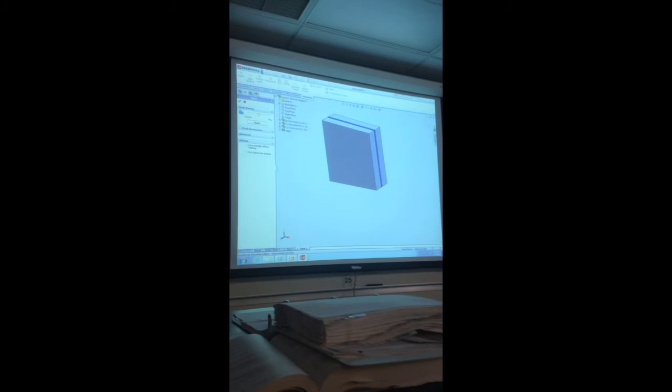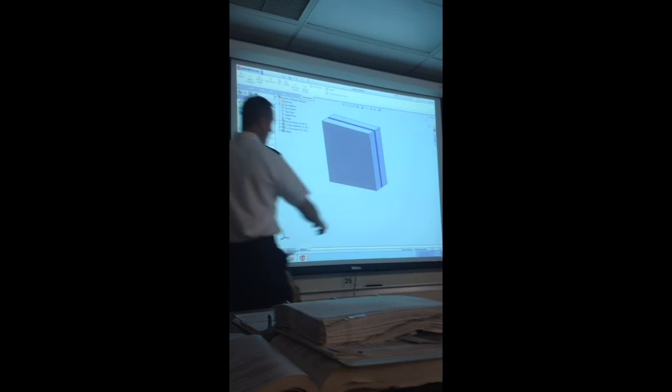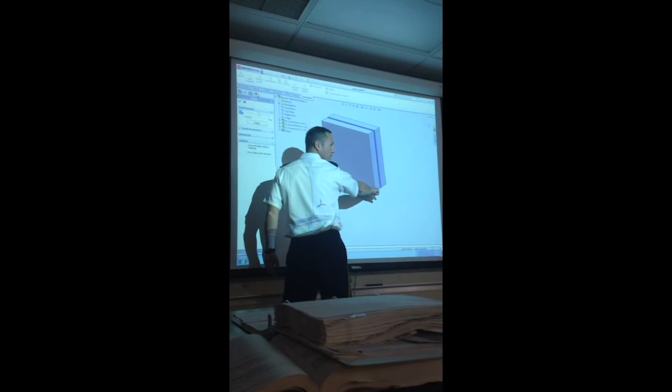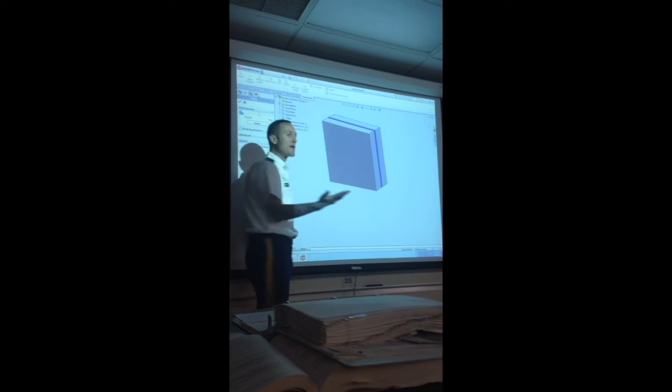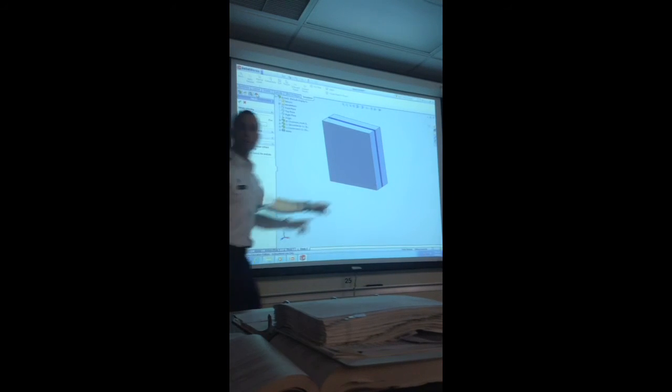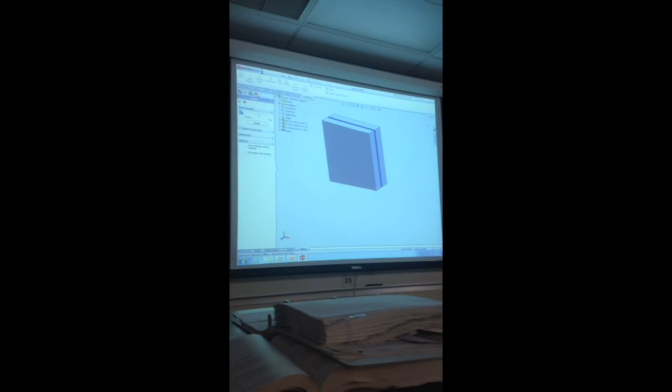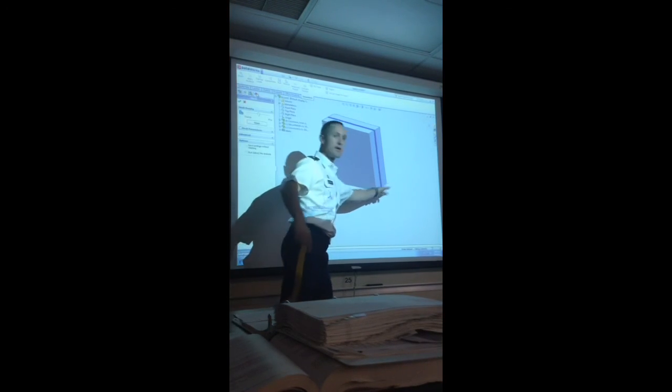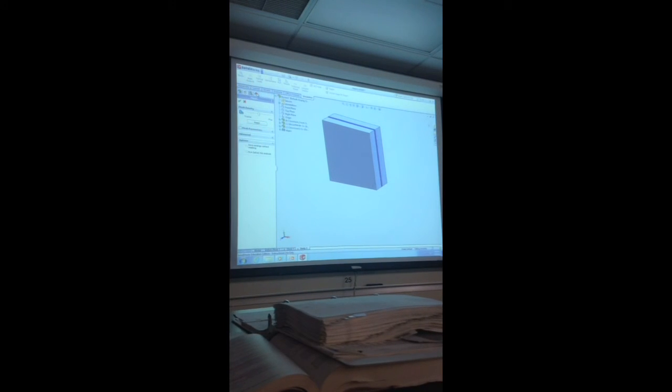And the results up here, it's reasonably intuitive, but you'll be able to do, for example, a probe plot. You can put your cursor right here and say, plot this as a function of time. Well, that's one of the graphs you have to produce. So it's an easy point to find. You can do a time history plot with 2 clicks or less, I think, where you can literally get an XY plot that shows the temperature at this point as a function of time, which is one of your deliverables. I think you have 4 of those points you want, and then of course it'll automatically generate the contour plot for you. That's the first thing that'll pop up. A very pretty contour plot.